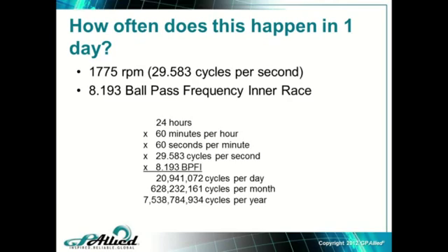So then you ask yourself, wow, it's any wonder that they last 5 times L10, which puts you in that 8 to 12 year range for most bearings. So when you take 7.6 billion times 8, that's a lot of compression cycles, a whole lot of compression cycles. So there's no way it'll last forever.